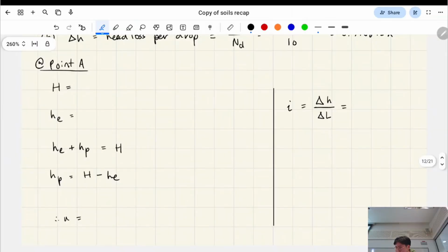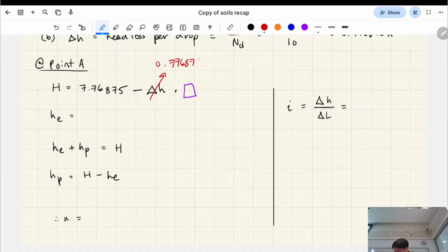Great. So here's how it works in terms of how the numbers plug in. Essentially, we're going to start at the area with higher head. That's what we calculated before, how many meters of head we had at the start of our system. And it's going to drop by the drop per head multiplied by how many squares we're going to do. So that's what I was trying to do in purple here. This we calculated, head per drop. This we calculated, that's the ratio thing that we did. That gives us 3.2694. So that's our total head.